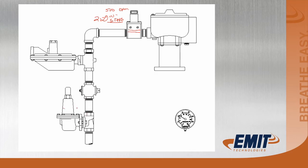This is a Little Joe. So this Little Joe, we're going to adjust the pressure on this based upon what this regulator range is set. If the max is 25, which would be common for a naturally aspirated small horsepower engine, we would set our fuel pressure coming out of this regulator, the Little Joe, at 12.5 pounds. Okay, that's middle of the range for the spring that's in this regulator. 25 would be max, 0 would be minimum, and so 12.5 pounds would be the starting point. Okay, so we'd start at this point.